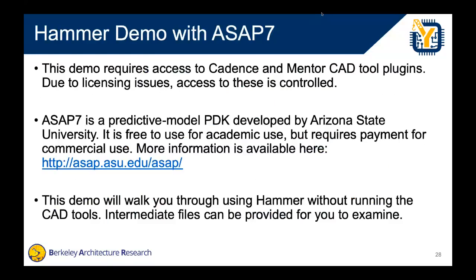So I'm going to walk through what a demo would be. As I mentioned before, it's hard to just give everyone access, so you won't have Cadence tools on your laptops, but I'm going to walk you through a demo that pushes a SHA-3 accelerator from Shipyard through Cadence and Mentor tools to generate a DRC and LVS clean design with Hammer relatively simply.